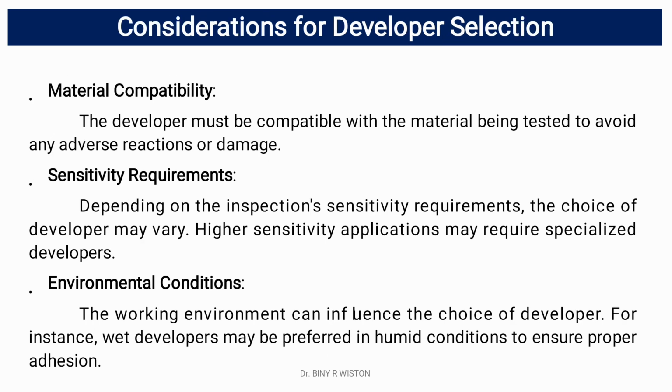Before considering a developer, the following properties are to be considered. Number one, material compatibility. The developer must be compatible with the material being tested. The second point is sensitivity requirements. Depending on the sensitivity, the choice of the developer may vary. High sensitivity applications may require specialized developers. Then the environmental conditions. Wet developers may be preferred in humid conditions to ensure proper adhesion.